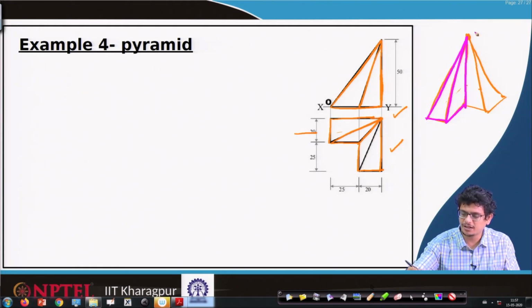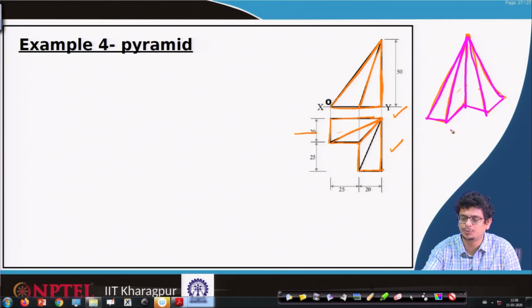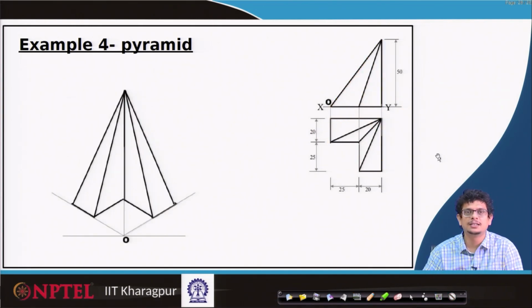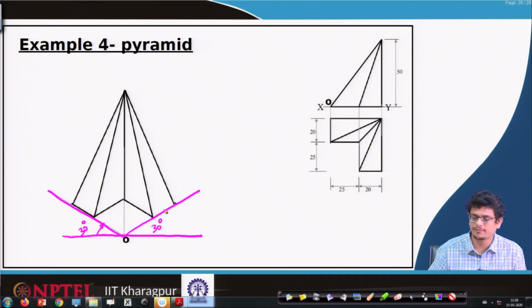As a 3-dimensional thing. Once we have that kind of visualization, we can go ahead and systematically construct such a pyramid. Please practice this example on paper, on a drawing sheet. The first step, as usual, is a horizontal line; draw 30 degree lines, that coincide by bringing this box into the system.